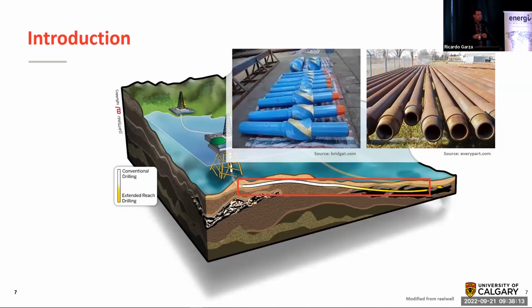Now, an interesting thing with drill pipe: if you think of 10 meters of drill pipe, so let's say this steel column right here, you expect it to be very stiff. You don't want this building to move. Now, what happens when this building is 7 kilometers tall? That little piece of metal becomes very noodly. So there's a lot of dynamics, a lot of movement that can go into it. And that becomes an extremely interesting dynamics problem that needs to be understood if you want to know what's happening down at the drill bit.